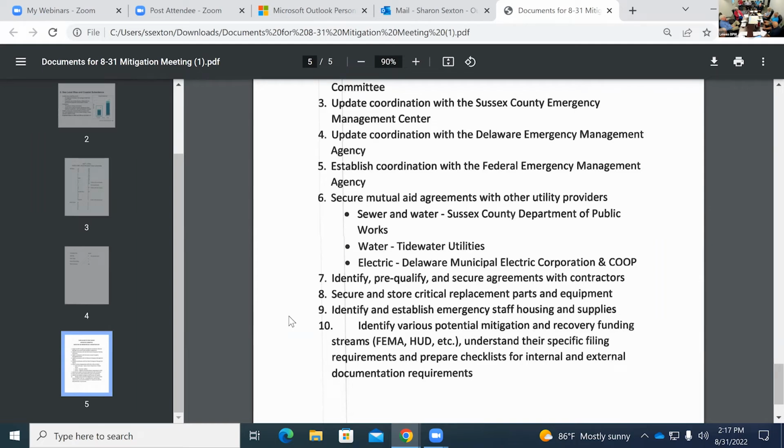And we're considering another one in the new road area. We put a casing across the street and took advantage of when all the work was being done on the road and the roundabout was being put in, so that in theory, when that time comes, we can put a piece of 12-inch pipe down, run it all the way down and tie in with Tidewater again. That one is used if the bridge crossing ever goes down and we don't have a redundant line through the Miller farm. We could isolate that whole side of town on that main by closing the valve at the bridge and still get fed from the new road side.